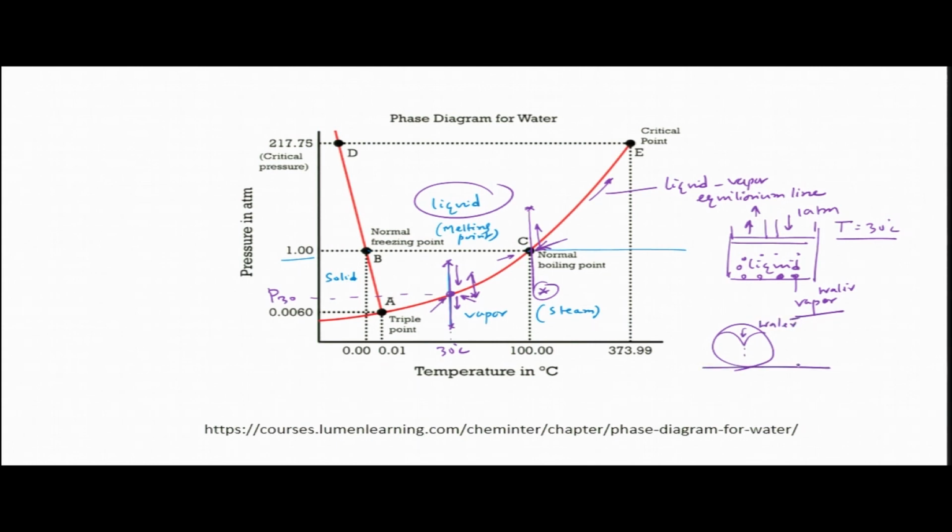This is a flat surface where the vapor has formed, and it is collapsing in this nature, and then the water jet will hit this surface. When everything collapses, this water jet will hit this surface, and this is the pressure it exerts on that particular surface because of the bursting of one bubble.